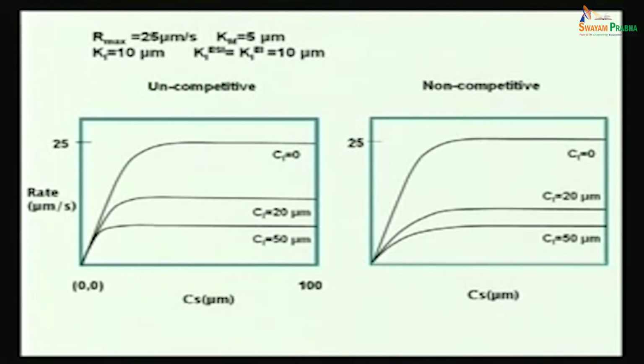So the total residence time is still the same. Okay, and if you keep the total amount of the flow rate the same, then you essentially divide up. So a 10-liter reactor, you divide up into four 2.5-liter reactors, right? So say your flow rate is 1 liter per hour, and your 10-liter reactor is there, so your residence time is 10 hours, right? Now if you split it up into 4 different reactors, your residence time is 2.5 hours each, and your reactor volume is 2.5 liters each.